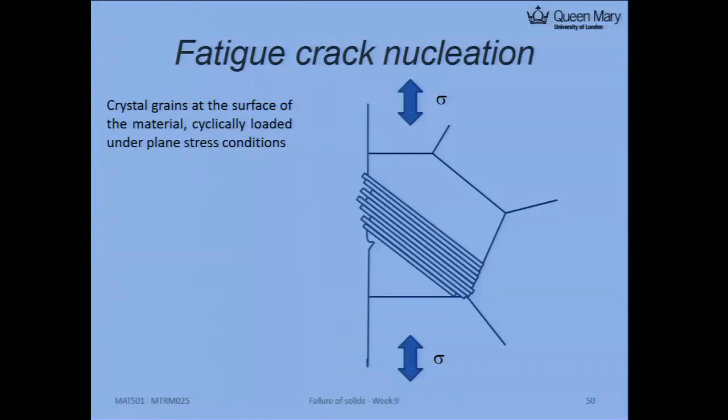Dislocation is a concept for a crystal like that. In micro scale, it generates some shear stress such that your crystal can glide along that plane, like what I'm drawing here. So a lot of slip happens. Slip is the motion of dislocation. Dislocation happens at the atom level, but at the micro scale you will see the crystal have these slip bands. It will generate a surface which looks like that, which we call intrusion or extrusion. Some of them are pushed inside and some are extruded out, like this shape.